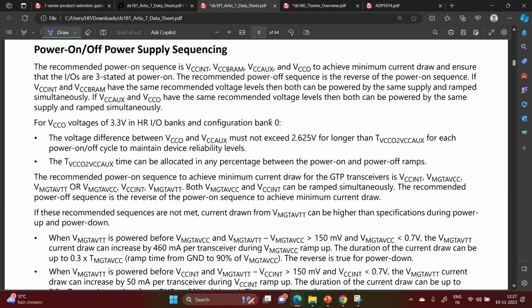Very good. Once we proceed to power on/off sequencing, once we select a regulator, whether it is a linear regulator, or a switching regulator, or our PMIC, power management IC. I'll recommend, if you have a very high-end application, but you can give a little bit of time in testing, go ahead with PMICs, unless a linear regulator is required. If you have a very tight requirement of noise or something, then you can go ahead with a linear regulator. Otherwise PMIC is much easier to proceed.